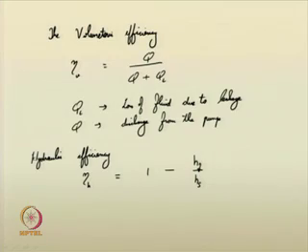So, Hf, the losses, can be of various nature. It can be due to shock, if some shock waves are generated or some shock is created, means abrupt interruption of water, that can create some loss. So, that is shock loss.